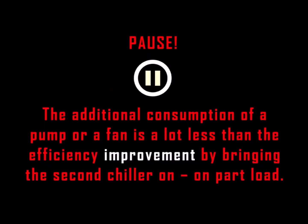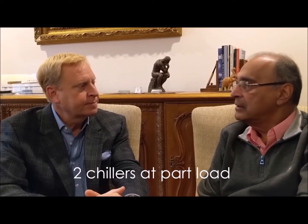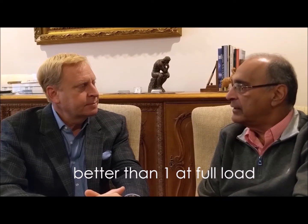Partly because the operators feel that by bringing a second chiller on, they have to also bring on a pump and a fan with it, and therefore there is some additional energy consumption. But what they fail to realize is that the additional consumption of a pump or a fan is a lot less than the efficiency improvement by bringing the second chiller on part load. And by running 2 chillers at part load, you're better off than running 1 chiller at full load and the other one at 0.